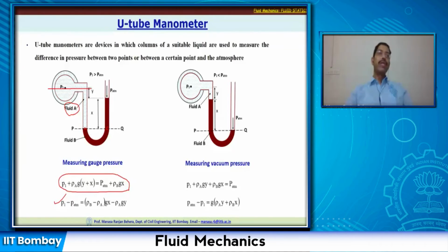Now the point that needs to be understood is, initially, when this liquid was not connected to this, the left limb would have been open, so you would again have P atmosphere on this side. If both sides are connected to atmosphere in the beginning, or there is zero gauge pressure exerted here, then both of these will be at this level.